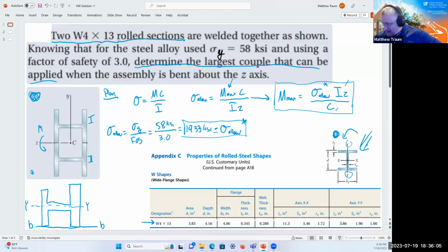So I've got to do two things here. I've got to first figure out how to translate this chart into a 90-degree rotated version of it to get here. Then I've got to figure out what happens if I weld two of these together along this line BB on this plane of symmetry. I'm doing those two things simultaneously as I'm solving. Remember, it's IZ that I'm solving for in this second piece. So let's grab the key information that we need. We're not going to worry about the XX axis, because remember, this is the YY axis that we're talking about. So we're going to use this one.